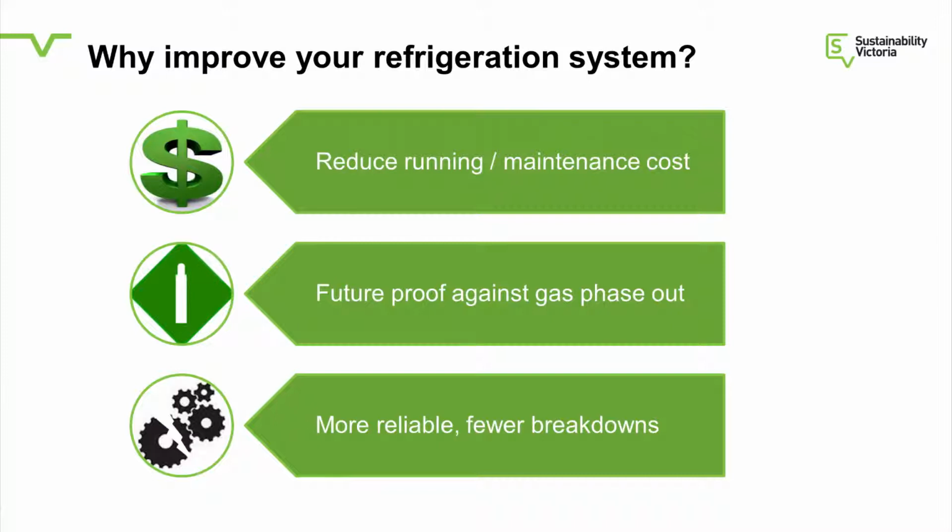And especially with the phase downs, refrigerant costs will spiral, and you will have greatly increased maintenance costs in future with the synthetic refrigerants. Good motivator to move away from them. Then you want to future-proof yourself against the gas phase-out. So if you're using R22 gas or one of the HFCs, there is a risk.